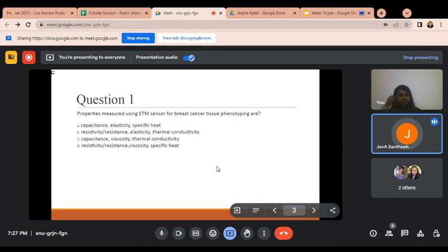Okay, ma'am. Actually it looks like a boat. In the boat we are taking that source, some material whatever we want to deposit, some gold or some nickel or some aluminium. Source means whatever we want to deposit, that is the source material, and where we keep it in the boat, the boat is called the source holder.